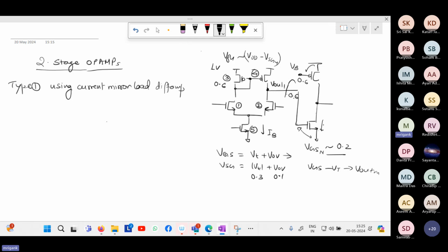It is increasing the overdrive voltage, and therefore IB2, the bias current in the second stage, will be increased because we are using a larger VGS for the NMOS. We are forcing the gate voltage of this NMOS to be dictated by the gate voltage of PMOS, which is higher. As a result, IB2 will be bigger because remember there is a square dependency.